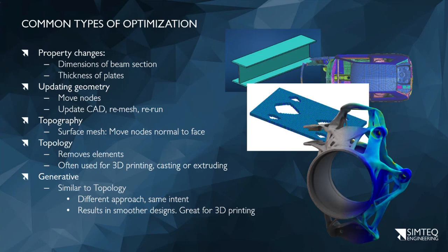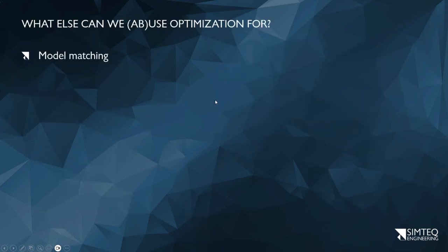So the cost there isn't related to the final material, because compared to my initial material, I may end up with less than 10% with the rest machined away. So that additional machining is actually more expensive. But the cost there comes in flying a heavy part is much more expensive than a lighter component. So that's why it's in that case really important to look at mass.